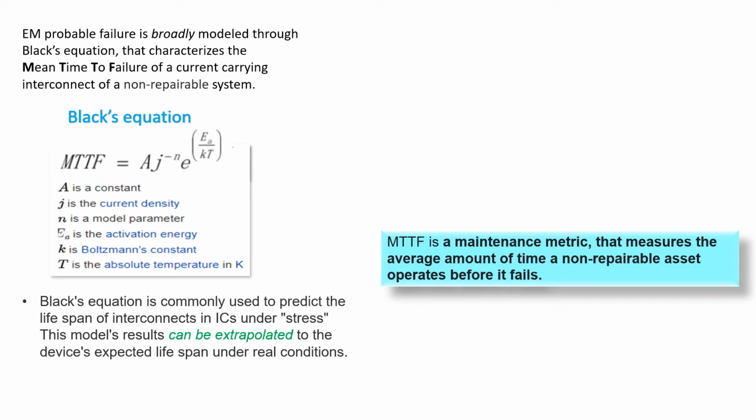represent the EM behavior fully. That means physically it does not represent it, but it gives a largely broader picture. Hence, even in lower geometry nodes, Black's equation is still used. It predicts the lifespan of interconnects in ICs under stress conditions.